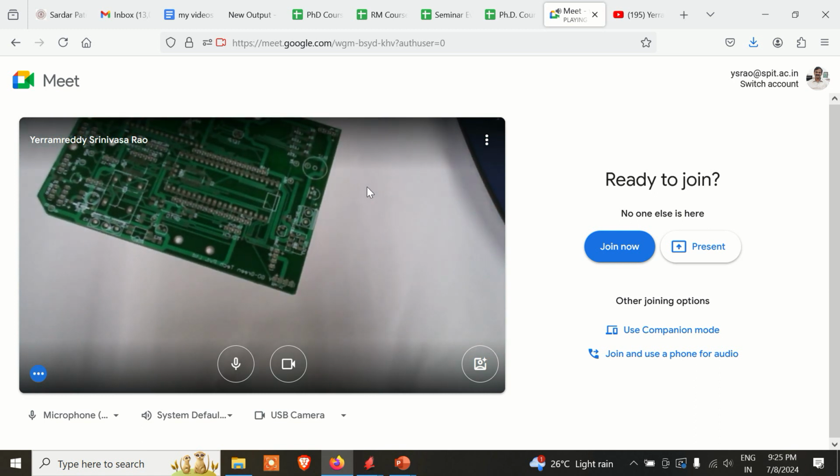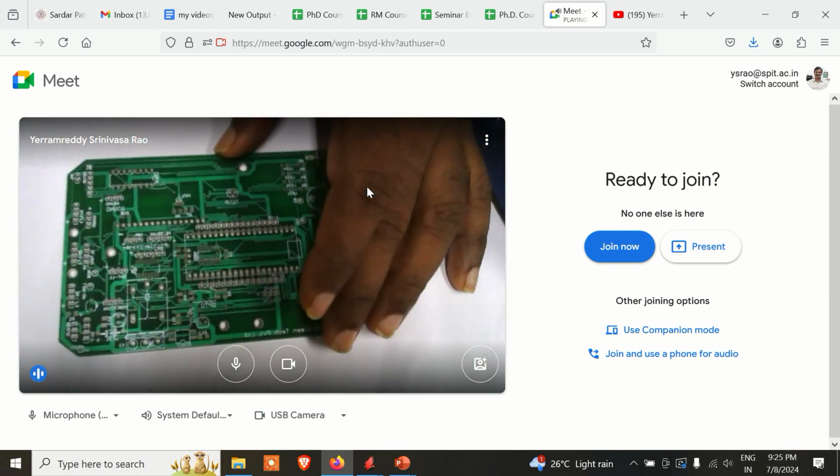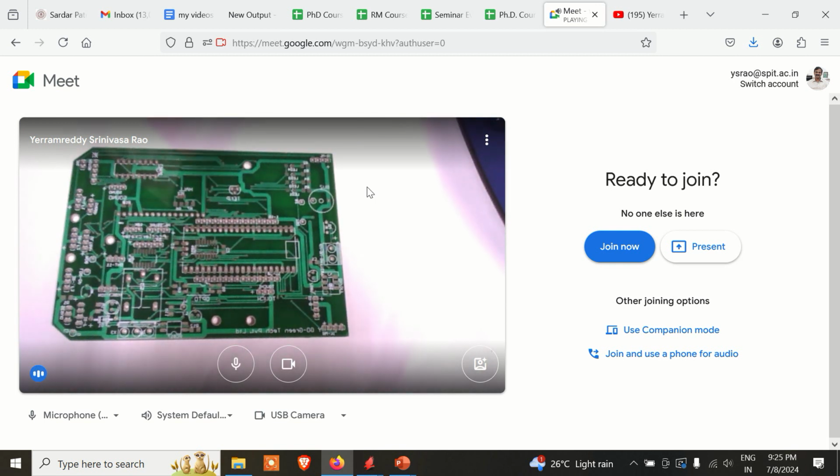That way you can verify these pads' top to bottom continuity before mounting any of the components. So this is the bare minimum test. Once this is done, let's start doing the soldering.